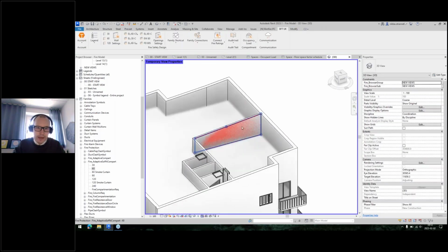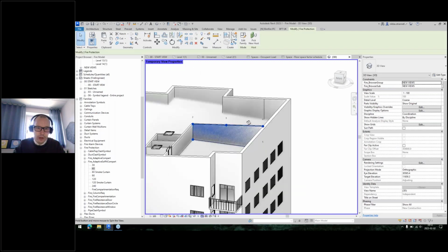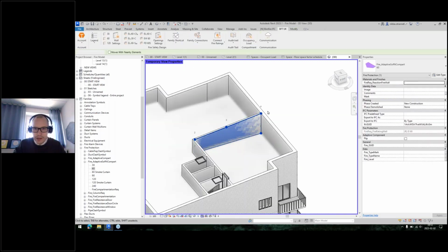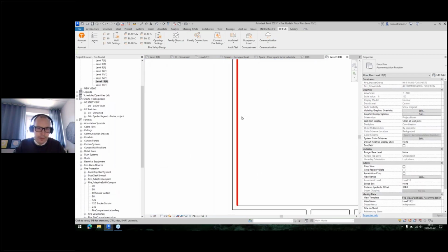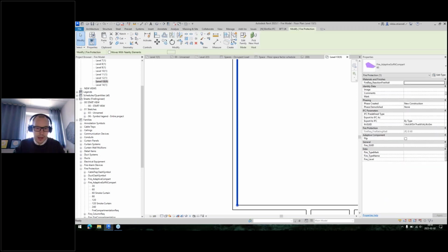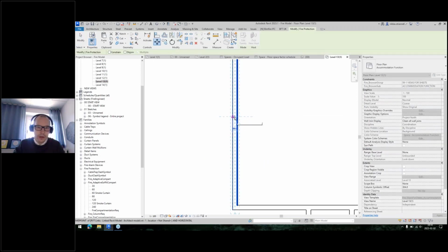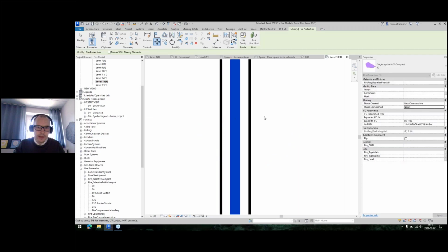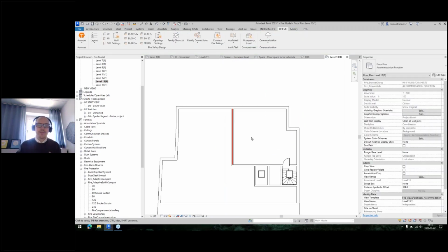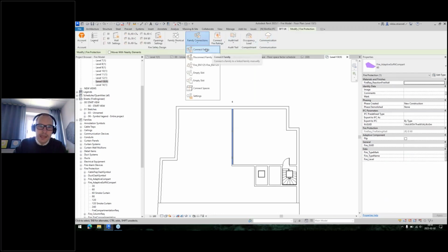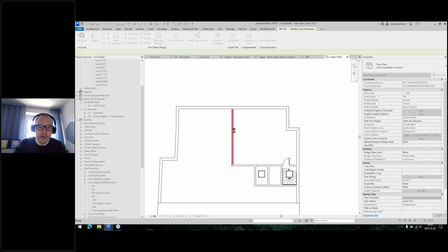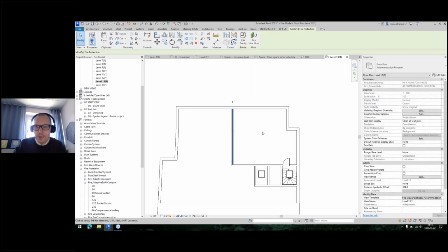This will automatically now have the shape of that wall. You can see it here. But it's not in the middle of the wall, of course, so we have to just go very simple, go to floor plan. You can see it here, and we can select it and move it into the wall, the center line. Zoom in a little bit, the center line, and we now have the same representation of that line within the wall, but it's gonna be a custom shape. Last but not least, we can then manually connect this to the underlying wall, so they are connected, so we can send that data with import mapping later on.